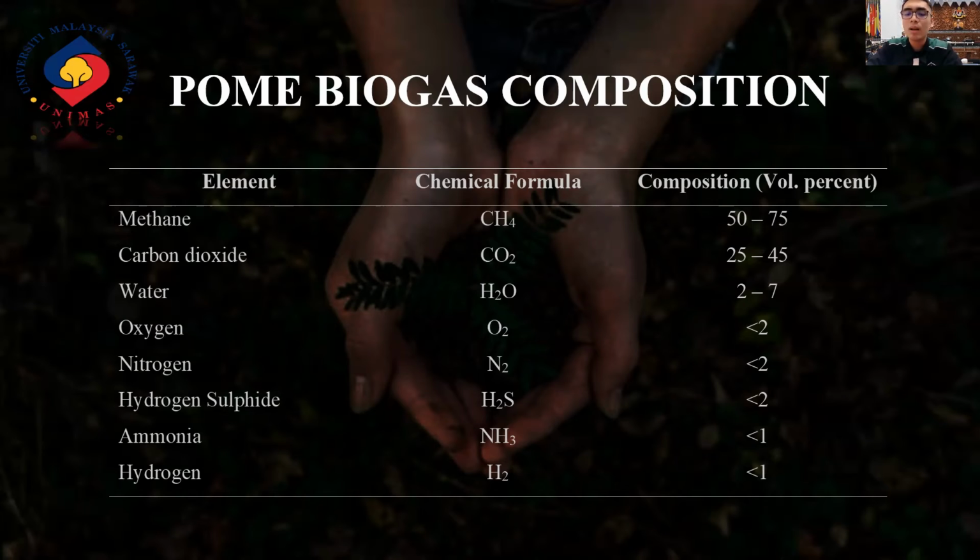operational efficiency. Besides that, there are other factors and variables that affect biogas production, such as pH, carbon to nitrogen ratio, and temperature. Those parameters provide a favorable condition for the microbes to digest the product into CH4 and carbon dioxide as the final product of the anaerobic digester.